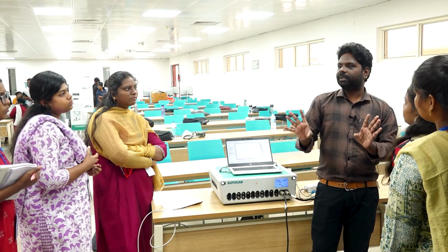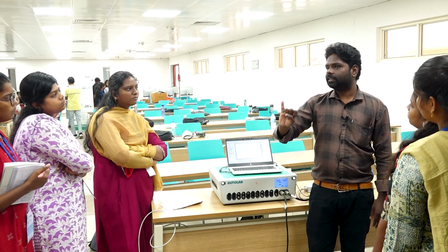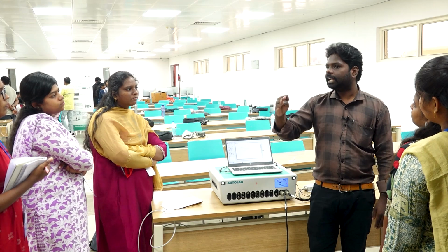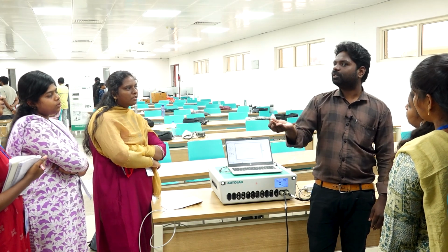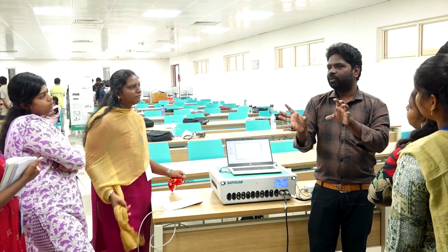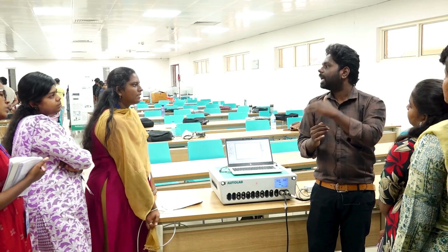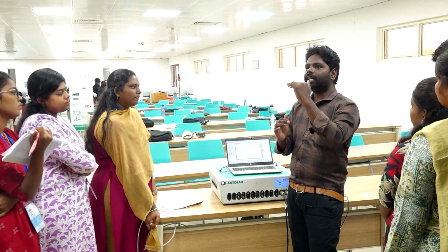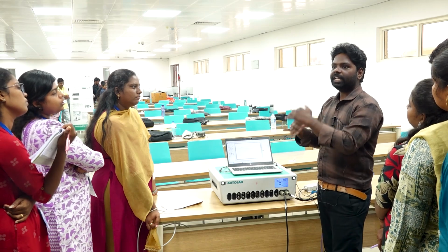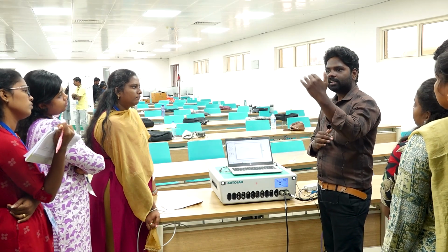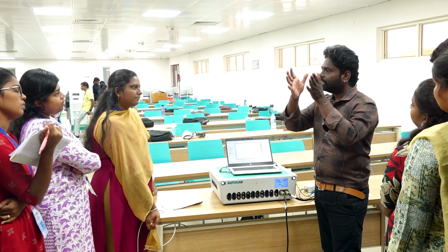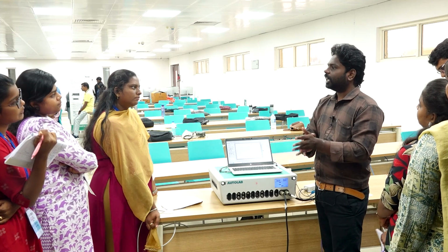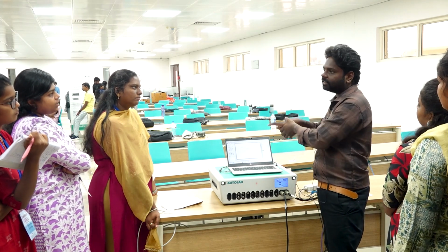Exactly. So double layer capacitance is building. Resistance is created, and at the same time, parallelly, capacitance is also building. So you observe this, both are happening parallelly, simultaneously. That's why we make the circuit in parallel. Resistance and capacitance both are happening simultaneously. So that's why we are making the parallel circuit.